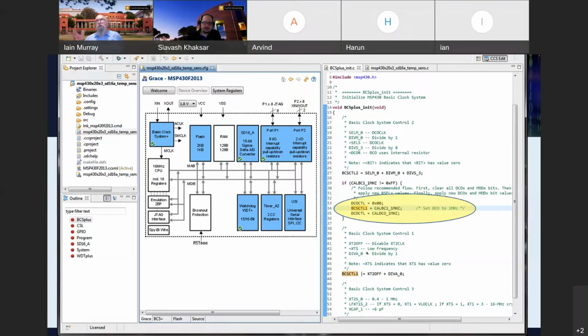So that's the first part. When you're deciding to develop your system software, it's fairly important that you choose the correct development environment. You can do early prototypes or things that are going to be very low product runs in things like the Arduino environment. But if you head towards larger production runs, where you need efficiency and to minimize the cost as much as possible, or in medical systems, you need to start considering these more complex and usually more expensive options.